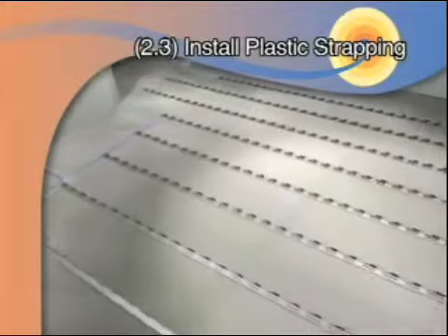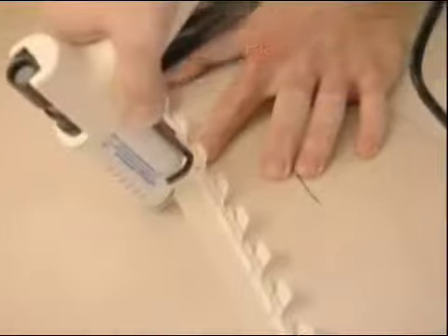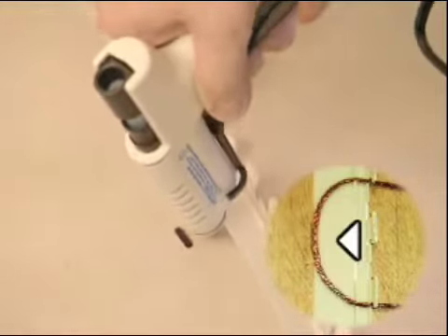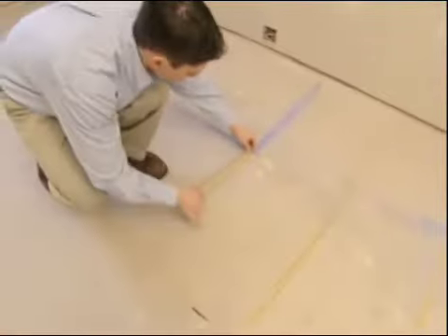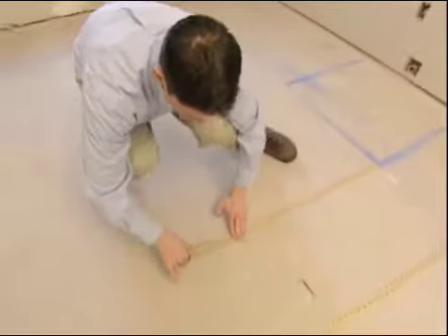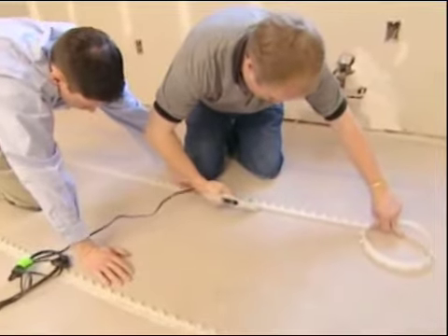The floor should be free of debris and other obstructions that may damage or cut the cable before you start installing the strapping. Install the strapping onto the floor following the planning sketch. Outside runs of strapping should be positioned so the tab clips will close towards the outside of all cable turns. Fasten the first end of the strapping to concrete substrates using the Warm Tiles tape kit. Alternative installation methods include hot melt glue guns or Tapcons. Ensure the strapping is adhered tightly to the floor.